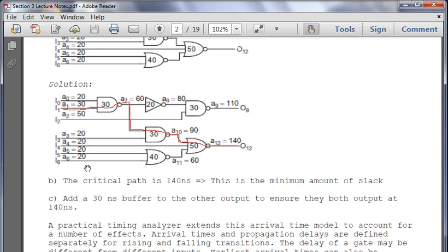So we're going to be going over some examples of how you can use some methods. The last problem we're doing in this section is a 6-input AND gate, and we have 4 different ways we design it. One, we have a 6-input NAND gate that we invert. One of them has 2 3-input NAND gates and a NOR gate. And one of them actually has 4 stages.